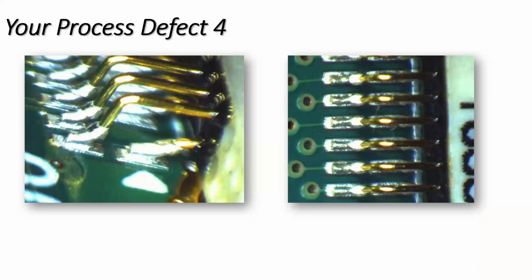So I would extend it there. If the pitch allows, I would have also extended it out as well. So you're getting greater volume of paste to fill up the gap and give you perhaps a more robust termination. Those are some of the things I would have done in this particular situation for trials on this particular part.